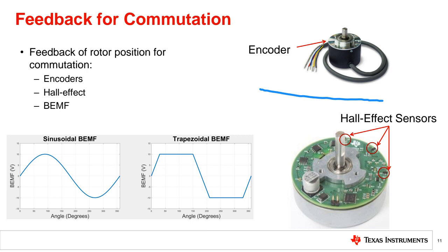Hall sensors are used in pump applications, HVAC, and air conditioner applications, where you only want rotor speed control or current control, because it's cheap. The price of 3 Hall sensors is maximum $0.5. Encoder, $100 minimum.